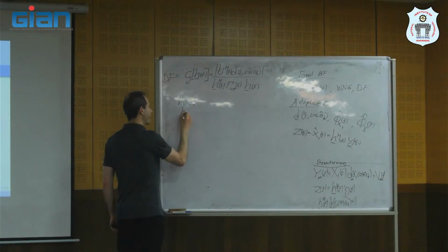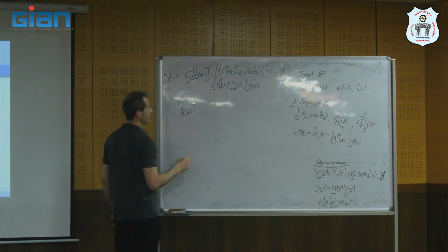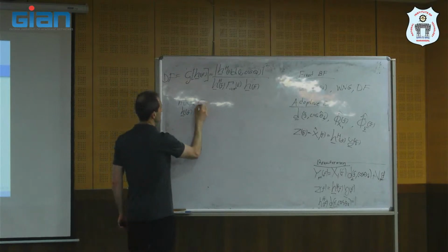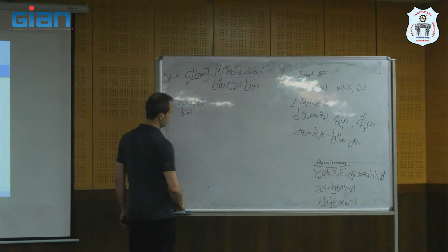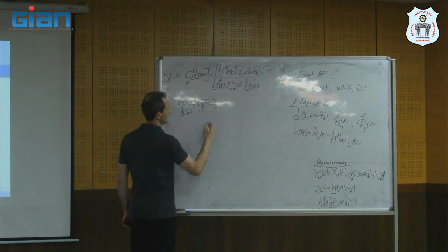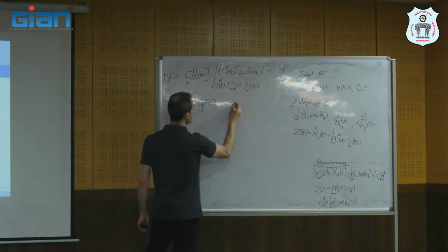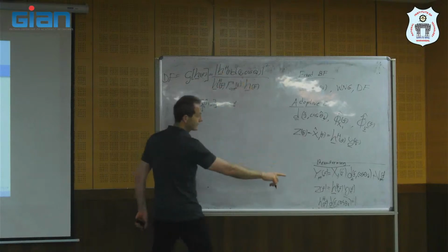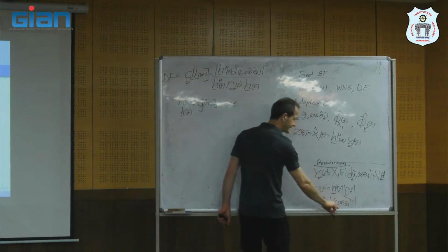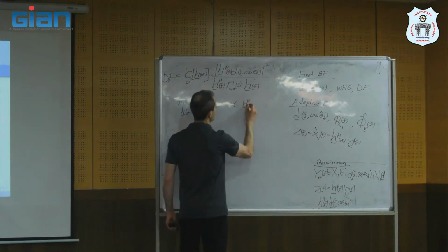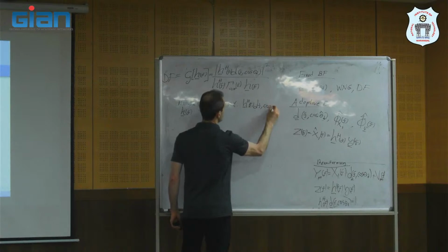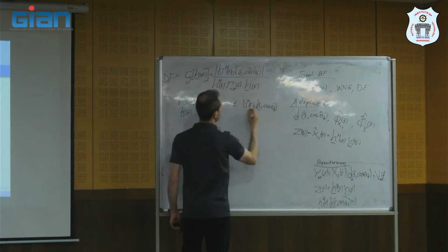So we try to find the beamformer h that maximizes the directivity factor, subject to the constraint that we don't have distortion for any signal that comes from the direction theta d, which means that h^H(f) d(f, cosine theta d) equals 1.